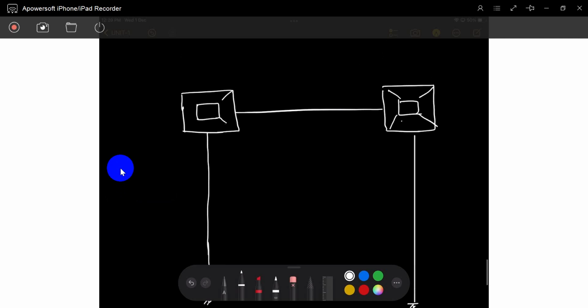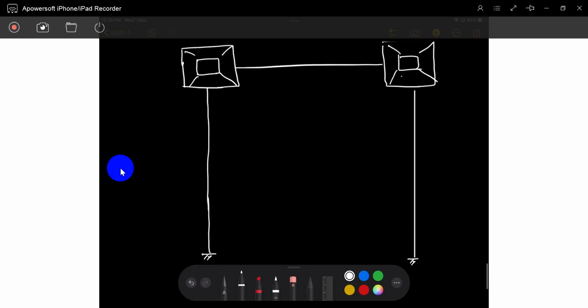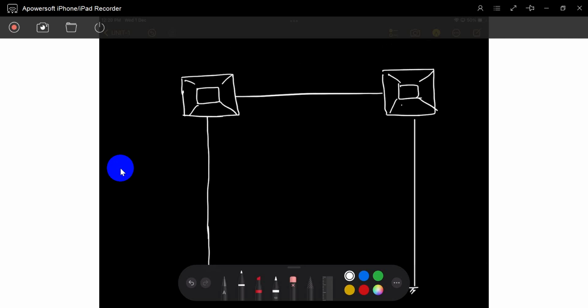You can write like this, same thing. Sum of the fixed end moments. See, first you have to write down the fixed end moments. What are the fixed end moments? Here it is 0, here it is minus 60, and here it is plus 60. Here it is 0.